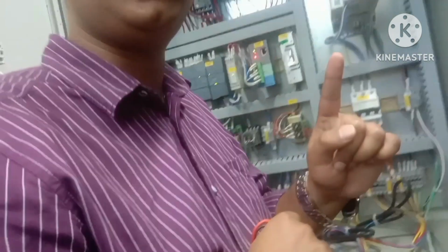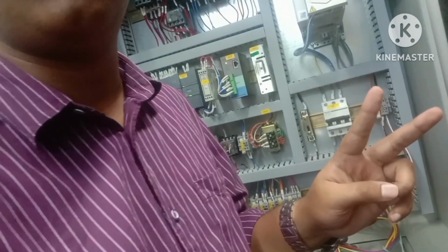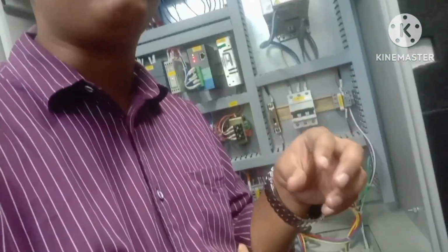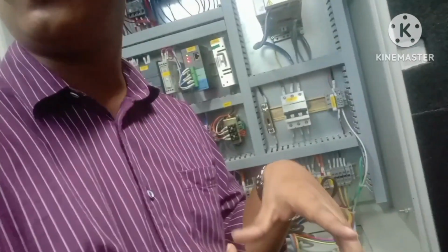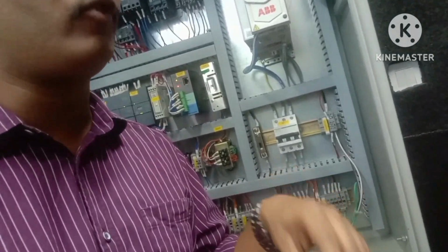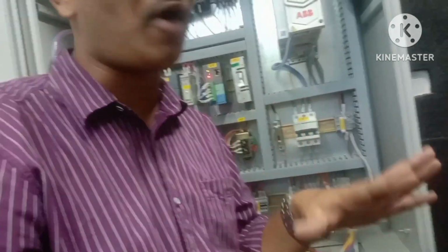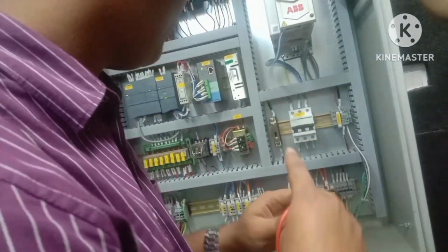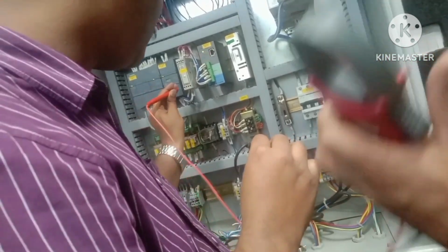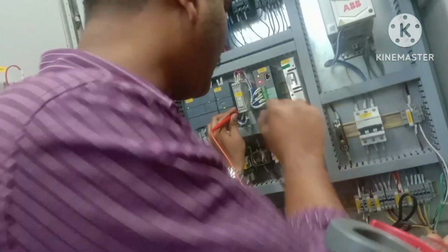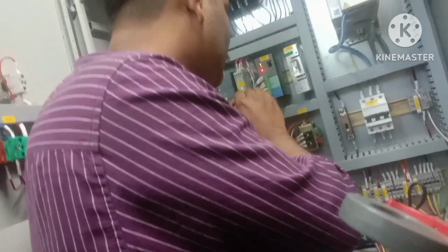As I told you, there are two types of inputs and outputs, basically IOs: first is analog and second one is digital. We get the feedback and we give the command only on the positive. As we control in terms of voltage 0 to 10, negative is common, or sometimes negative is grounded. So if I insert the positive terminal into the analog input and the negative terminal to any common, let's take N24.